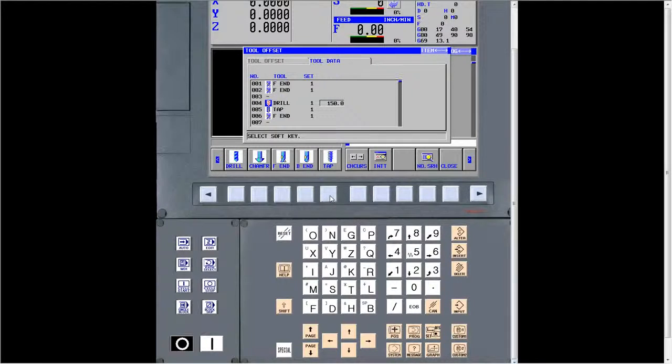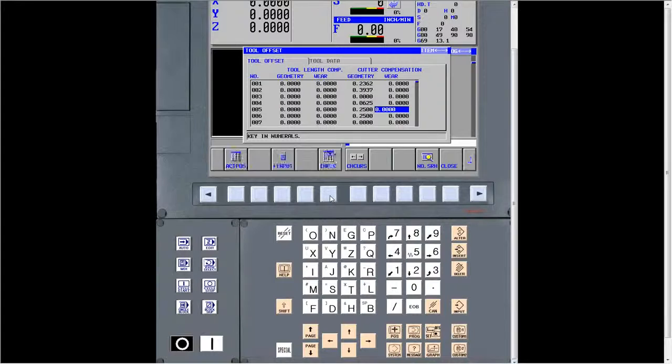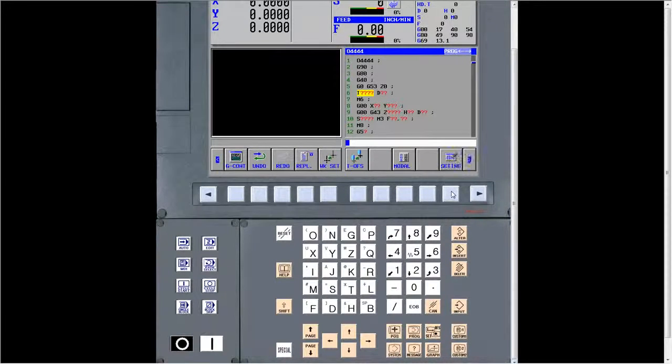So we know that tool number 5 is a tap, and it's a 1/2 inch in diameter. So we use tool number 5, so 5, alter, and then 5 alter on the diameter. Then we go down 0 on our positioning in X and Y. Then Z 1 inch, then alter that.